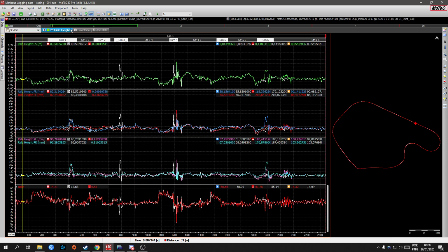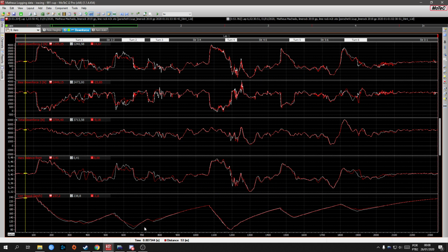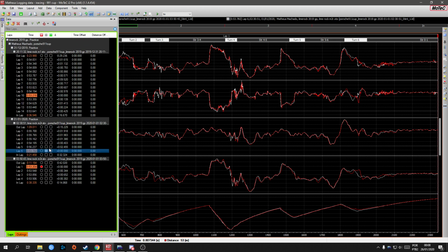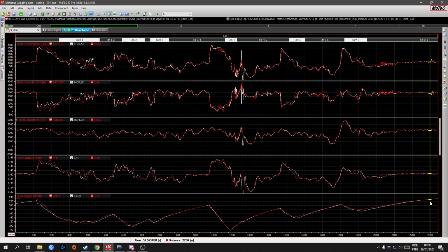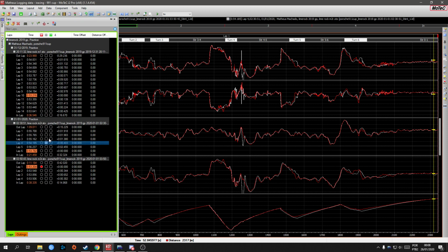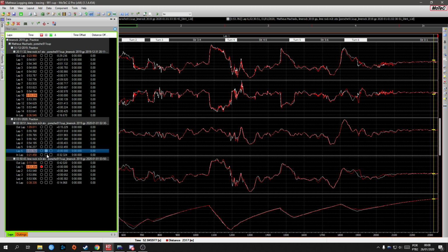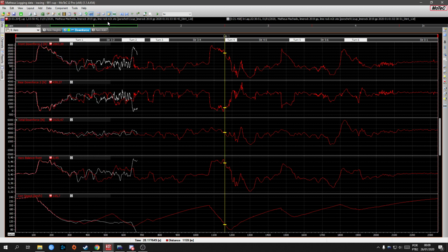downforce. But when I look at the speed graph, you can see that the red graph, okay, there is a little bit of better driving, but if you go scrolling through the laps, you can see that the red has a slight advantage in top speed. And why is that? Because it has less rake, so it has a smaller frontal area, which generates less drag.